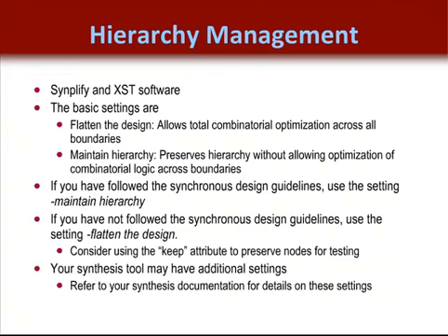So in general, we tell our customers to leave this optimization across hierarchical boundaries off and only use it later as a final last-ditch effort to gain timing closure. Fortunately, most customers don't get this desperate, but we like to mention the proper use of your synthesis tool here so that you have the ability to debug and simulate nodes later. Now, all synthesis tools will default to not allowing optimization across any boundaries. However, if you choose to enable this optimization, only enable it across the boundary associated with your timing critical path and never allow it to be used globally.